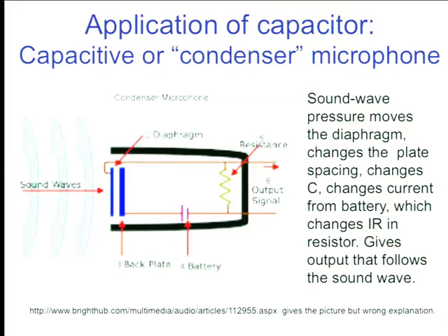So then you put a battery in there, connect it to a resistor. And in order to maintain the battery voltage across that circuit, some charge must flow to and from the capacitor. And you measure that current flowing through the resistor, which produces a change in voltage, which you then put in an amplifier, and then you send it on its way, and you've got a microphone. You've converted sound waves into electrical fluctuations on a resistor, which you then send down, and that's your condenser.